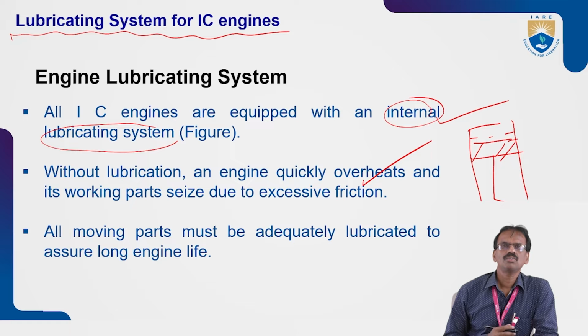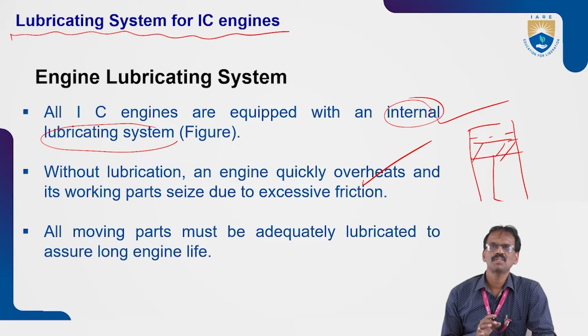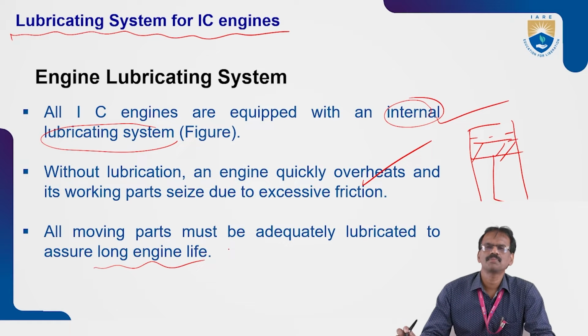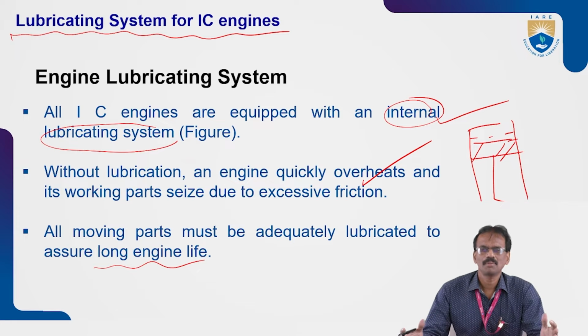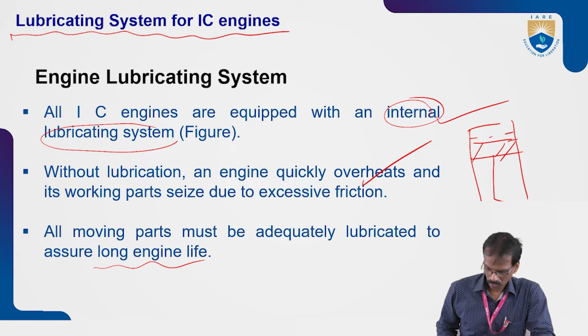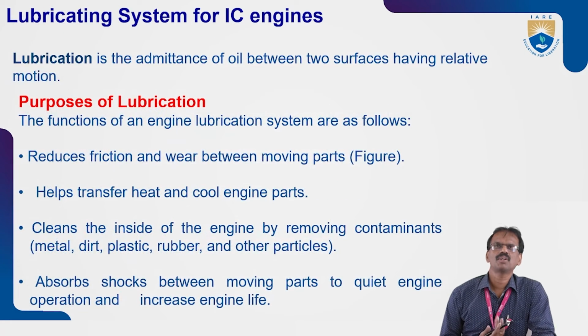All moving parts must be adequately lubricated to assure long engine life. So we have to provide sufficient lubrication between the two mating parts. Otherwise, due to rubbing and friction between the moving parts, high heat will be generated. That heat leads to damage of the parts. So the lubrication system is very important.